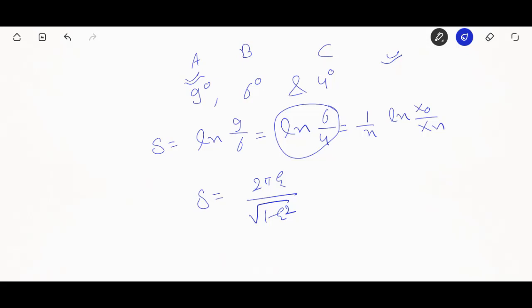Now, since we are talking about the torsional pendulum, this is a new case where torque has more involvement to calculate the natural frequency of the system, stiffness, and other values. So I would like to take this discussion towards the torsion cases. Now, if we calculate critical damping in this situation, previously I told you the formula would be 2 under root km. For this case, it is 2 under root of the torsional stiffness, which is why I am representing it with kT, and the polar moment of inertia.